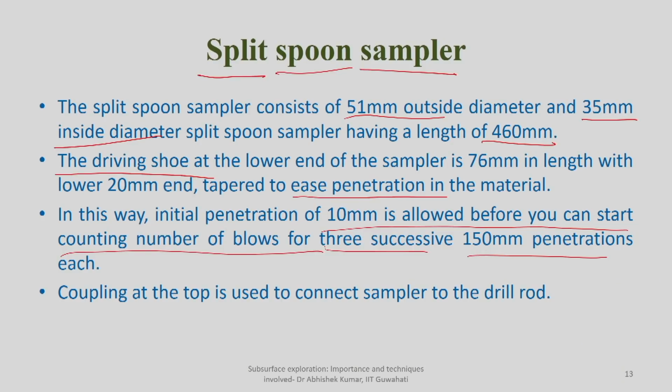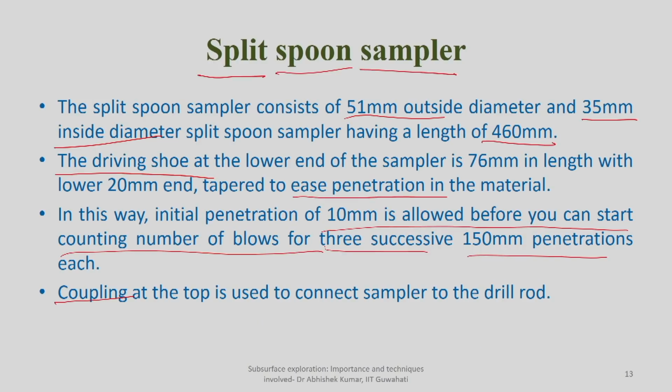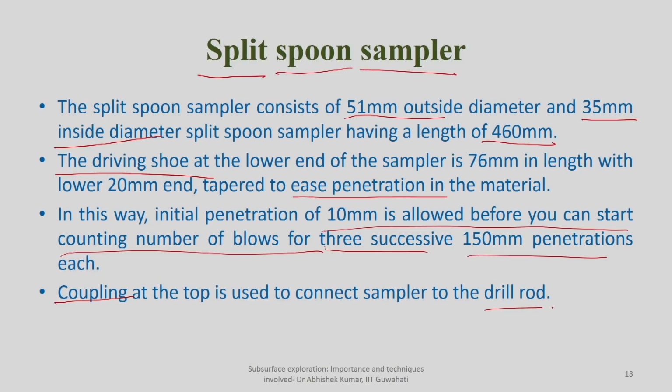Because you have to apply some kind of impact load, you need some kind of coupling with which you can connect your drill rod. The drill rod will be at the top, connected to the sampler, which may be at 5 meter or 6 meter depth. From the sampler to the top surface you will have the drill rod, and at the top of the drill rod you will have some mechanism which can apply impact load.